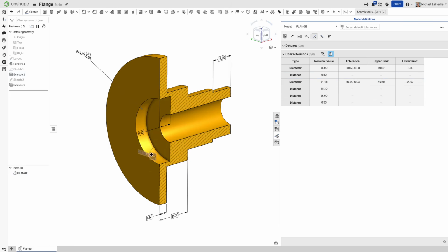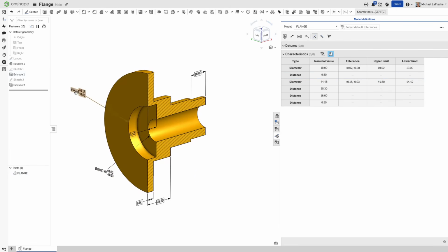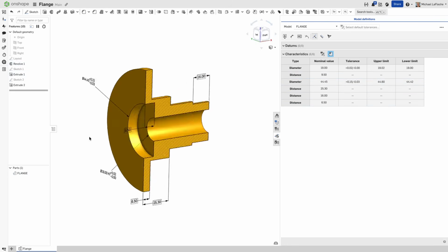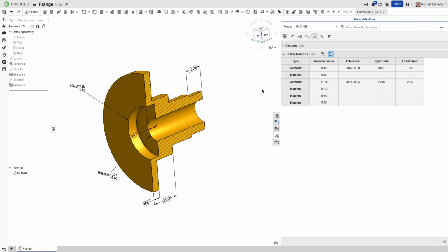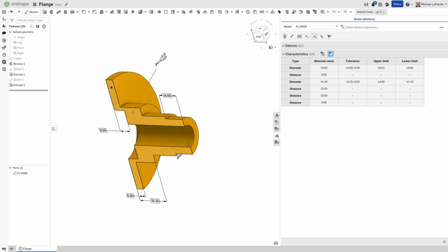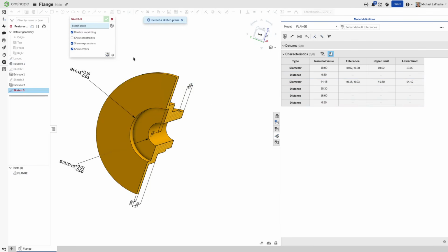I'm applying a hole tolerance with a hole fit, a transitional fit, for this right here. So that's also included. It's not just numbers you have to type in. You can pull from standards. Not only standards for holes, but standards for entire tolerances, like ISO tolerances and ANSI standards and things like that.